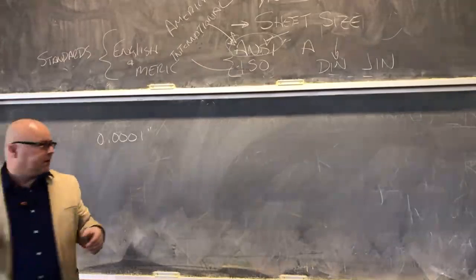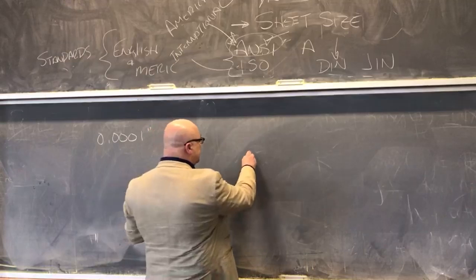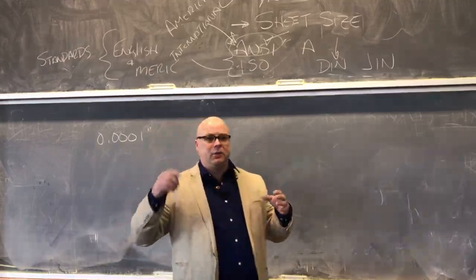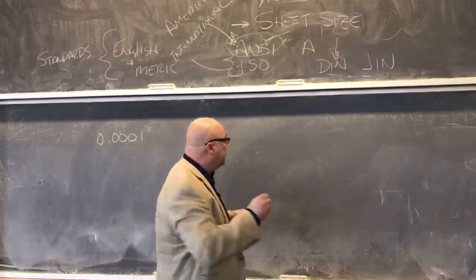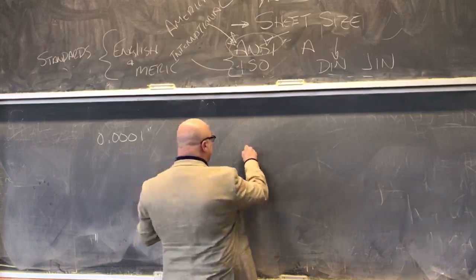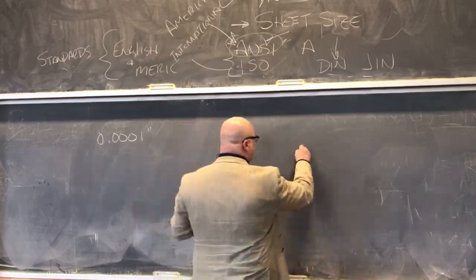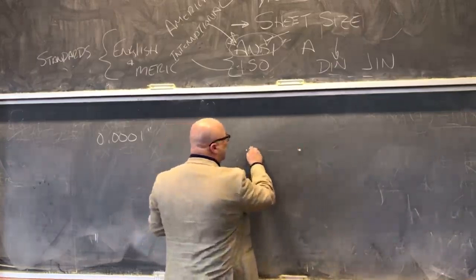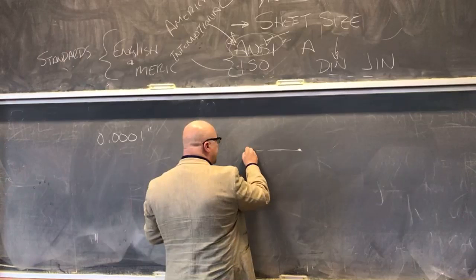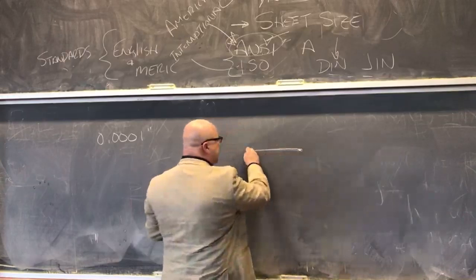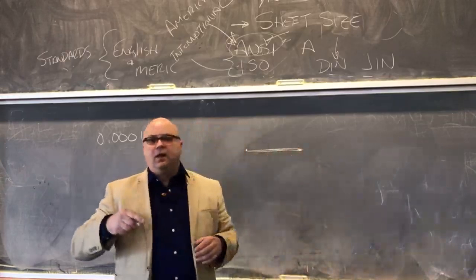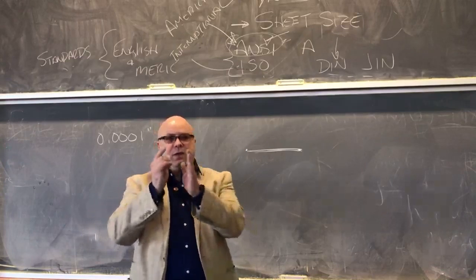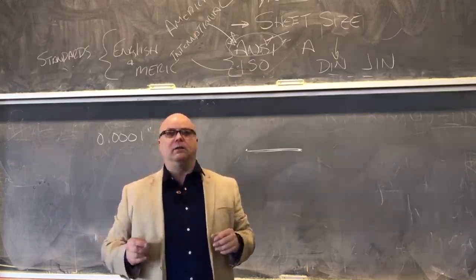It's not quite accuracy. What we mean when we say this, the repeatability of the machine, is if I move from here to here, and then I move back, and I move back to here again, and I move back, and I move back to here again. What's the chance of me getting to exactly the same spot again?